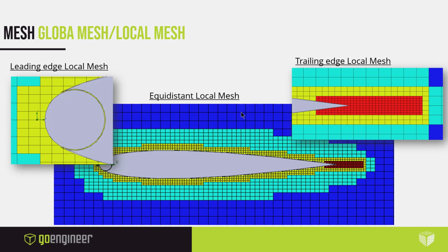All right, so different options for meshes here. I was focused on the leading edge, so I put a local leading edge mesh here just to basically wrap tight around. But as you can see, you're going to need to refine the mesh here to capture some more accurate data as it goes around this cylinder. And I'll probably need to open that gap up too. That's what I'm saying after I've run this study multiple times here.